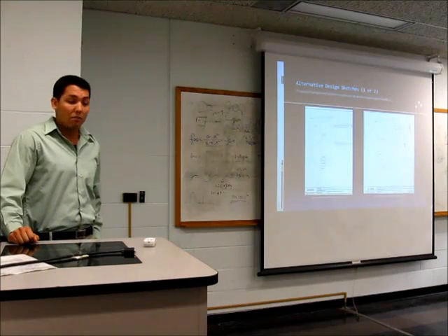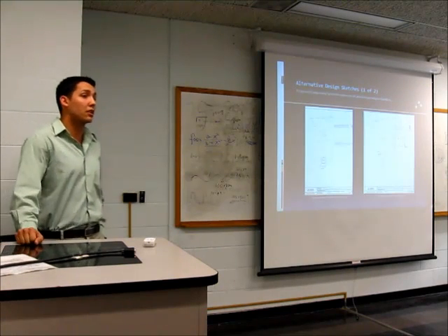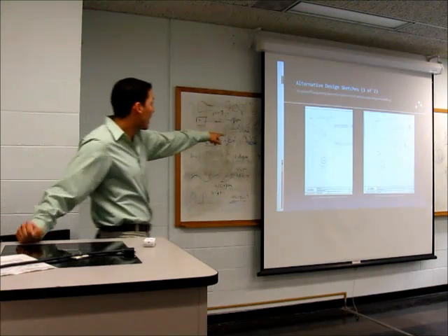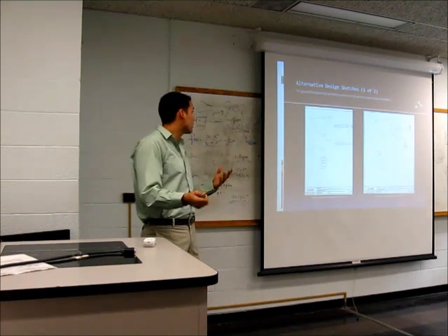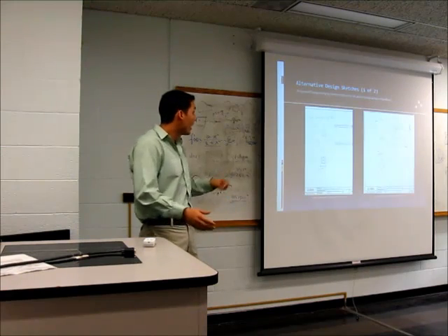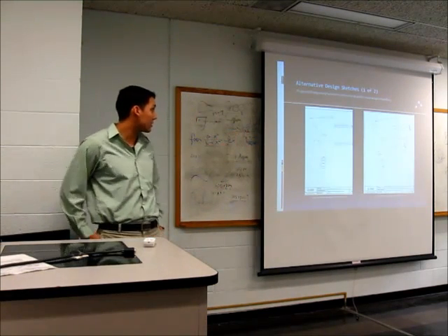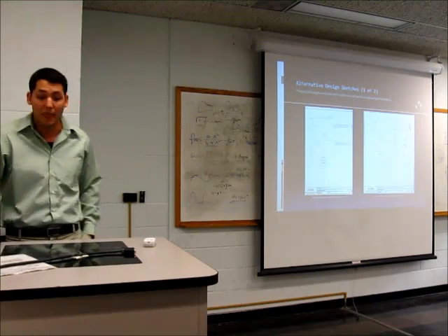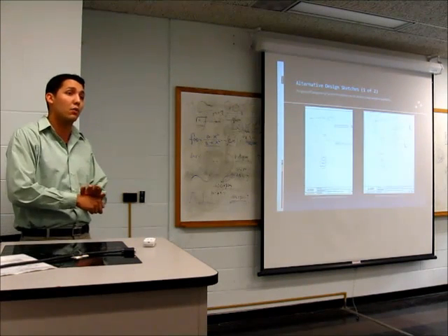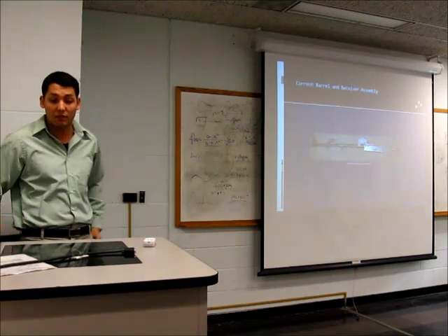Alternate designs. Because there's so much of a kickback, I wanted to create some kind of a dampening system for the spring. Here on the left-hand side, I came up with an idea to work with the guide rails to work against this little cap at the end of the spring. And also I had on the right-hand side a sketch for a rubber dampening system, so when the bolt group comes back, it can contact with the rubber dampening system and significantly slow it down.